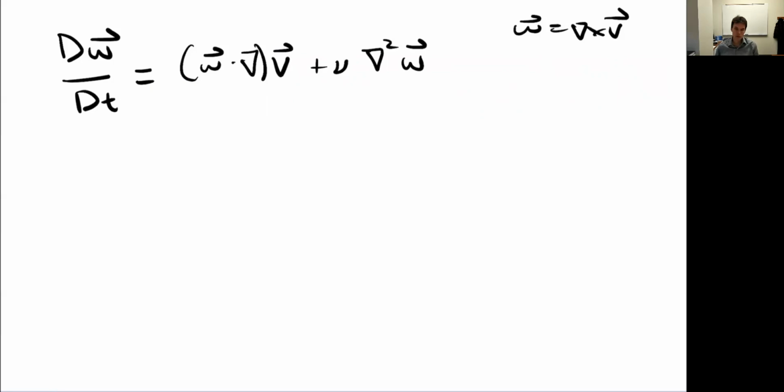So it's a bit of a debate whether doing 2D RANS is really useful. Perhaps it's more accurate to use these lower fidelity methods, things we talked about early in the semester, like a potential flow solution combined with the integral boundary layer method. Maybe that's a better approach, even though it's lower fidelity. In practice, though, 2D RANS tends to work quite well. So maybe it's just more of a philosophical debate, but it is something to be aware of as an aerodynamicist, that you'll hear this about 2D turbulence and whether that makes sense.